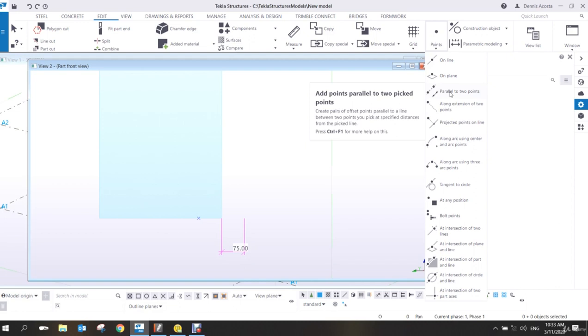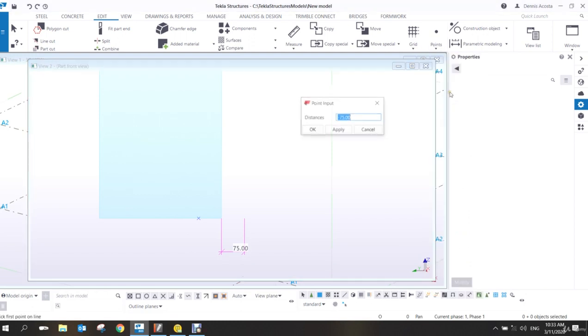So from here, offset. If I click on this one, same box that I will get here, but I will type 400, but the offset I want 475. So similar thing in grid line. If we put a space, then that's another value. So if I type 400 space 75, what will happen? It will offset 400, and then from 400, 75. It's a relative value again.